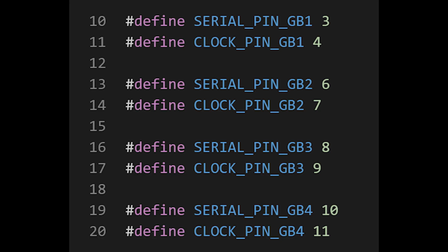Now, first things first, to get our Raspberry Pi Pico control software working with the additional GPIO pins of our 3 new Game Boys, we'll first need to take care of some defines that provide us with some set values that we'll be working with later on. First, we'll define each GPIO pin used in our system individually, so that we have a dynamic reference to the values for which the pins will be initialized and addressed later on.